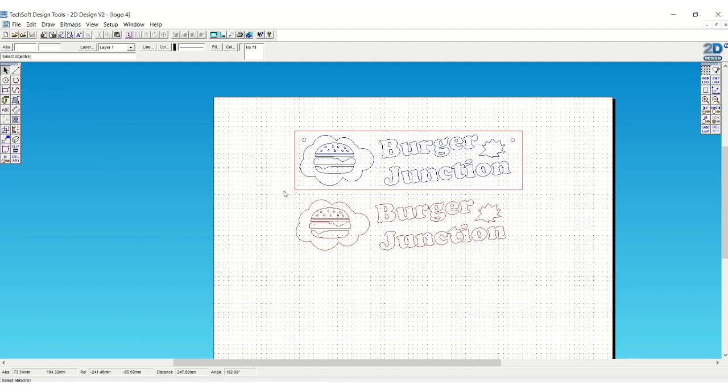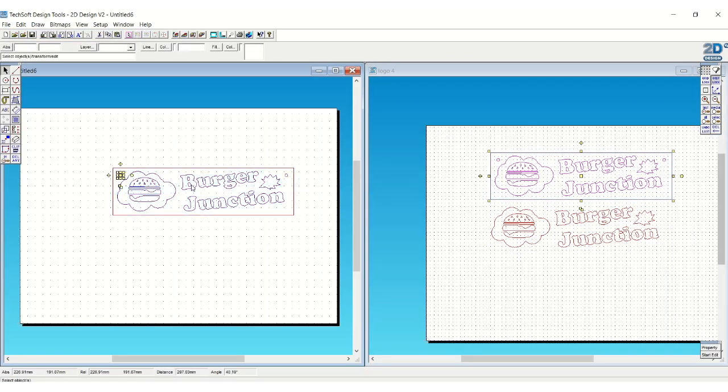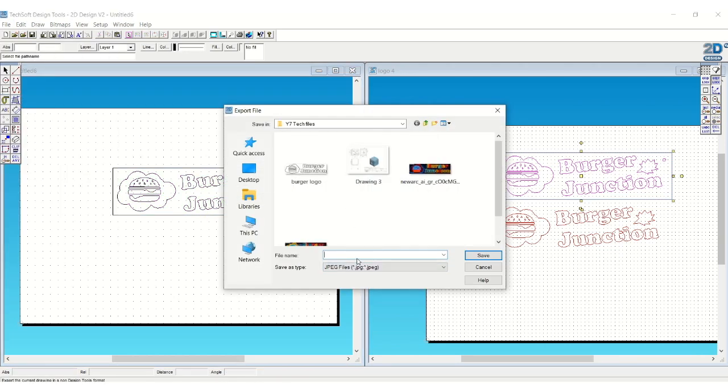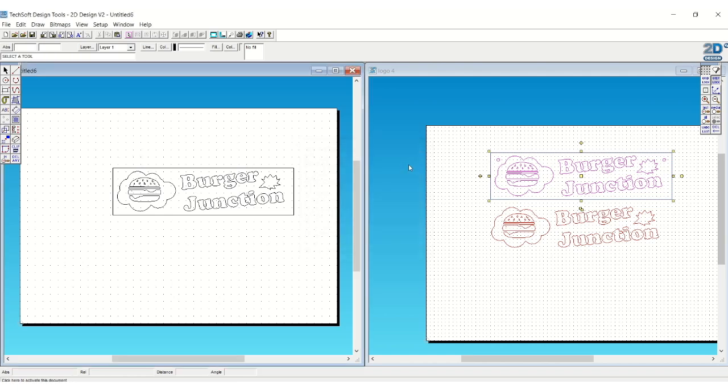So here I'm going to select the one with the box and copy, and then file, new. I've got the files side by side and paste. I'm going to delete the two little holes because we don't need those for AI. And select the whole thing and turn that black again and export it. So now it's black, export, JPEG, that's fine, and burger 2. Okay, and save. That's okay. And I will now have that file ready to work with.